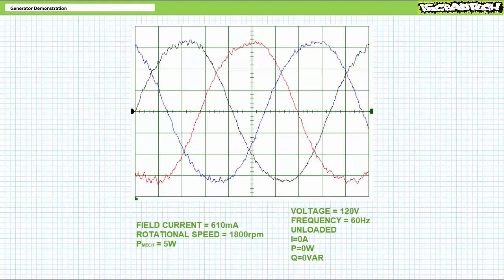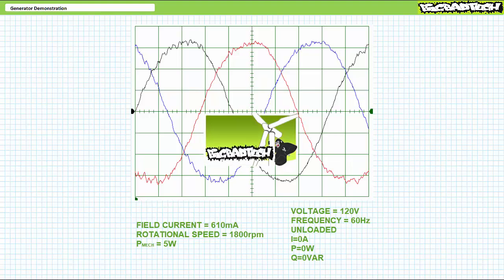This might describe one or two situations, but more commonly, as the grid experiences increased demand, additional generators are brought onto the grid through a process known as synchronization, something we'll examine in greater detail in later lectures. As we'll learn in this upcoming lecture, once a generator is synchronized to the grid, the pooled inertia of all those generators operating in time with one another largely keeps frequency constant. This is, by the way, a simplification of what we'll soon learn is a rather complex topic. Until then, this concludes this lecture.